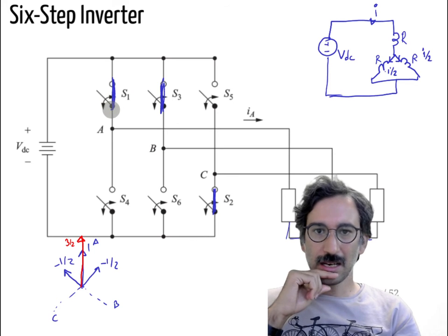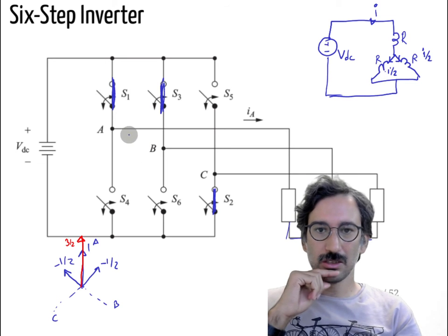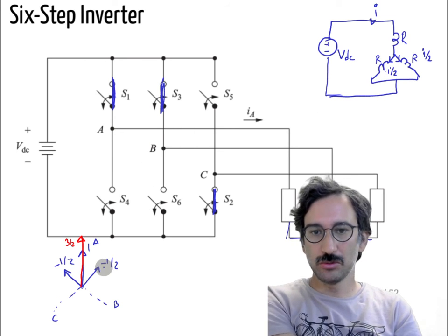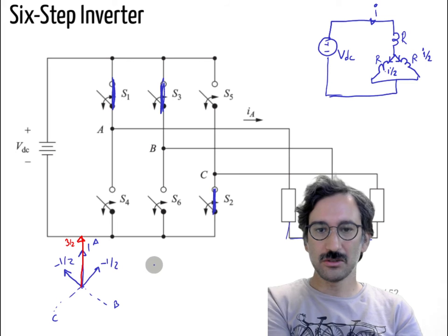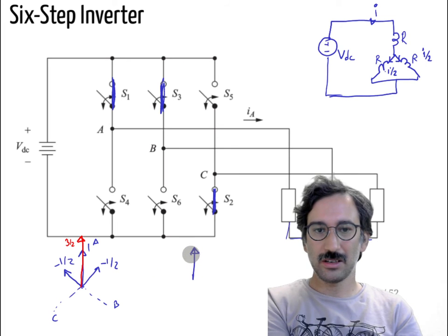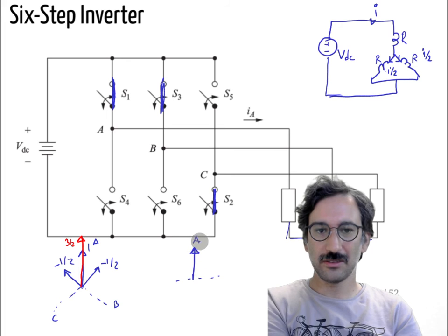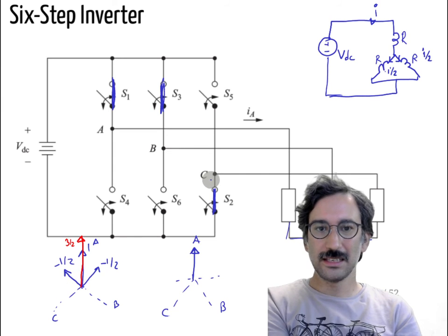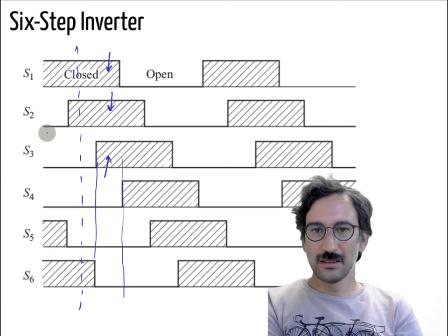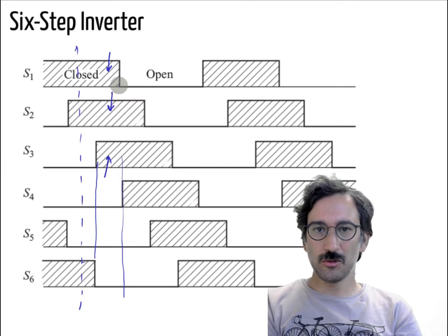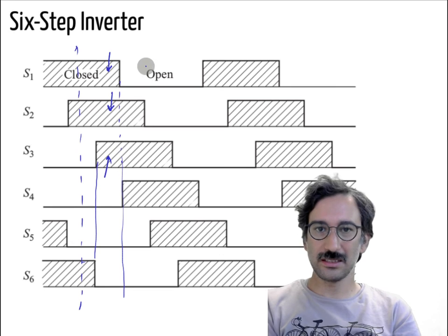So now A and B are connected to VDC. A and B are carrying I over 2, and C is carrying minus I. So in the first position, the MMF or equivalent phasor direction was like that. Now it is aligned with minus C, because C is carrying minus I current, so it comes to here, right? Then I move one step more, which is 60 degrees later on.